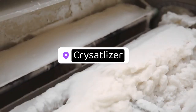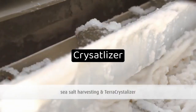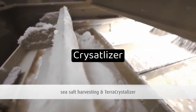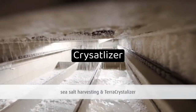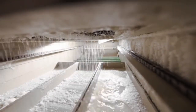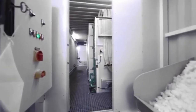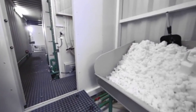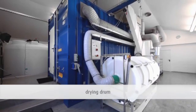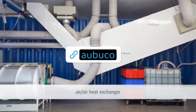Through the targeted control of concentration and temperatures in the entire system, it achieves an excellent purity of the salt obtained. Furthermore, the control of the grain size is realized in this step. The freshly scooped salt enters into the drying drum after draining. Here the salt gets the desired dryness. For drying, the residual heat of the system is made use of.